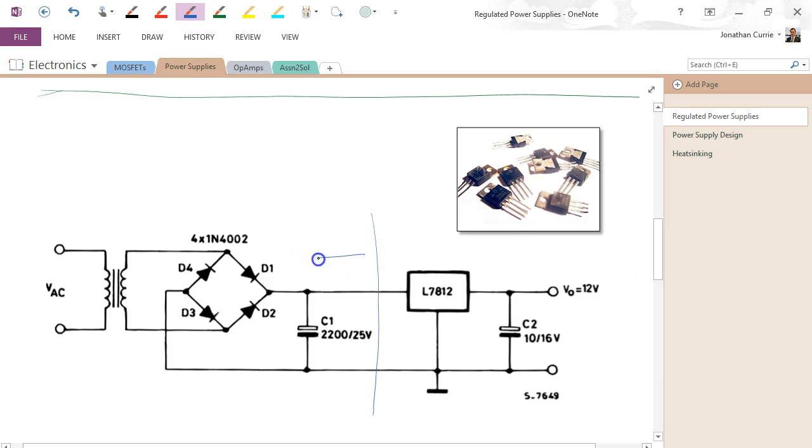What we're going to do instead is we're going to keep all of our existing circuit. Alright, so everything on this side is the same as above. And what we're going to do instead is add in one of these, what's known as a 3-terminal voltage regulator. And they can look like any normal IC basically, but very common are they in these TO220 packages. Alright, so very, very common that you pick up a device that looks like this. And the only difference is that it gets connected in series, so V in, V out, and to ground, and we have an extra filter or smoothing capacitor on the output.